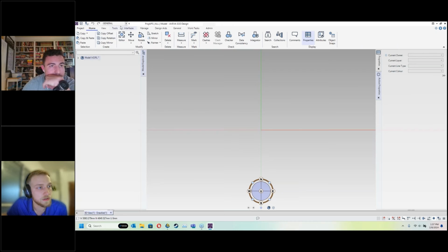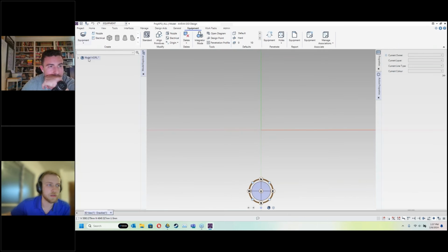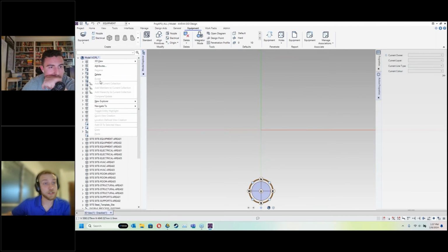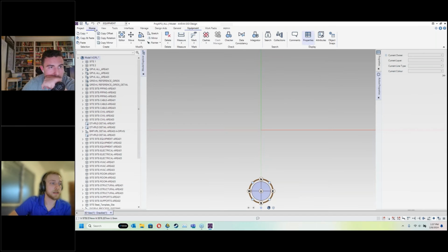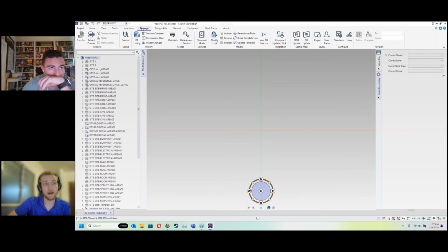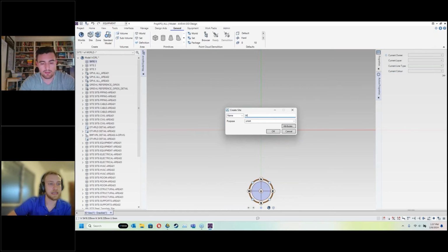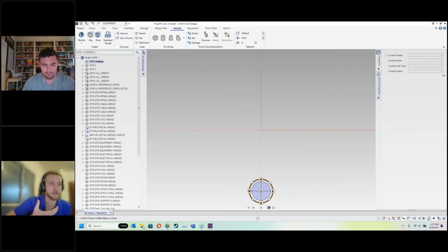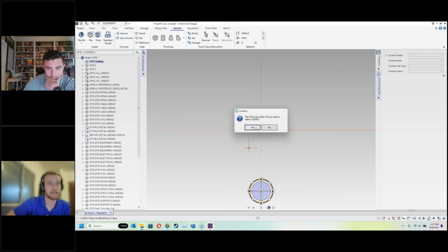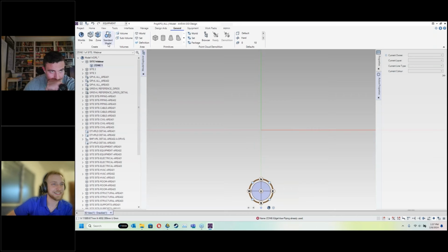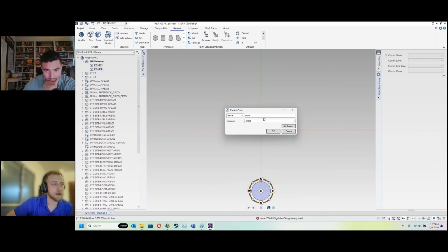Piping first? Yeah, let's go ahead and do the equipment import here. So as I mentioned, this is going to be equipment, right? For E3D specifically, as of right now, we are doing equipment objects, but the key here is that we try to keep as much logic to make them as valuable as possible. So when we do a valve or a flange or a T or reducer, it's going to be a sub equipment that's in that piece of equipment. We have the flange, it's classic. You should be able to just drop it in on the zone.